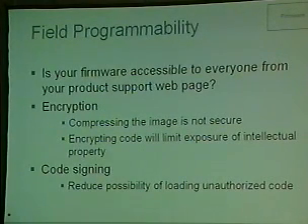Still weighing the benefits of encrypting it over just code signing. If you sign your code and you have your public key or verify key embedded in the CSOC, you'll at least be able to verify its integrity. So if somebody else changes your firmware in some way, they won't be able to run it on your processor because it'll fail the check.